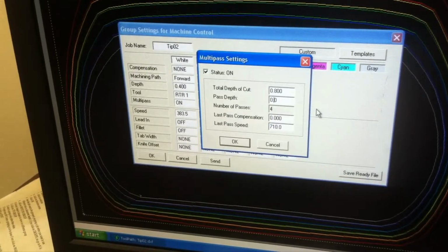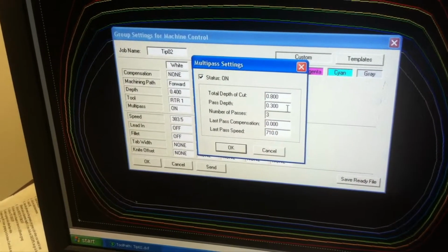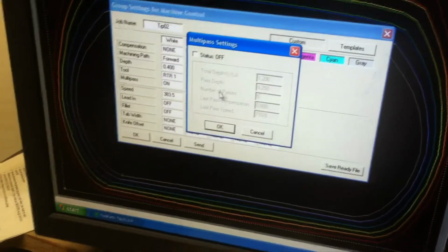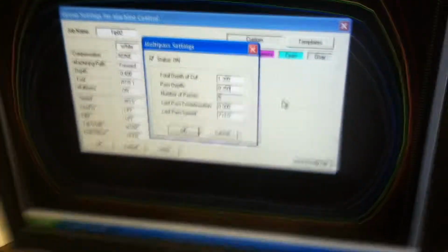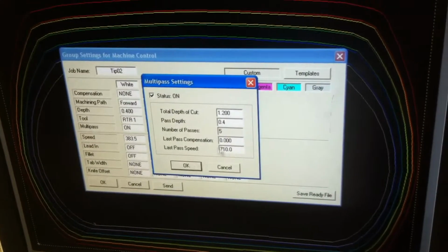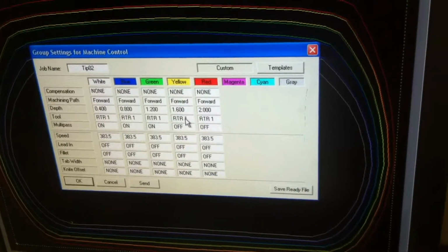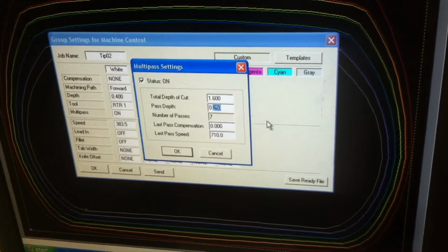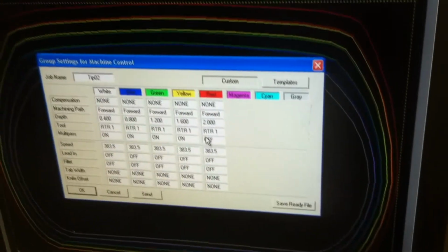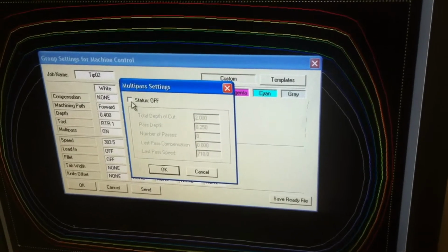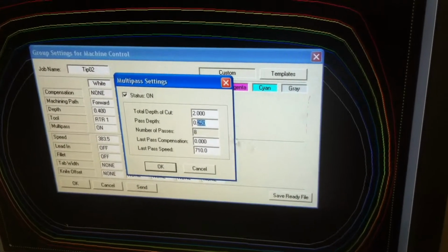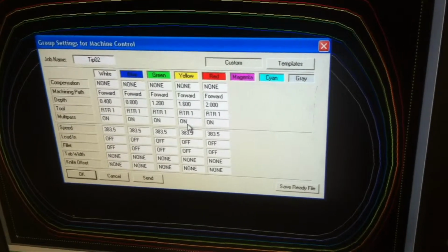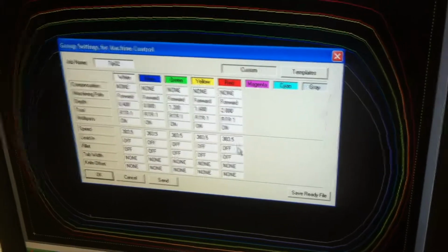So this one will take a little bit more. 1/4 inch. We can do 0.3. It'll take 1 less cut. And then here, this one I'll go 0.4 on this one. Why not? But I wouldn't go more than 0.4 for a cut, because then the foam melts. Well, and you also have to account for the actual cutting area on the bit. Other than that, this is ready to go.